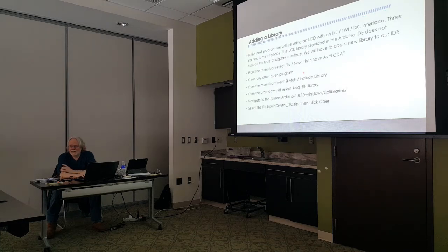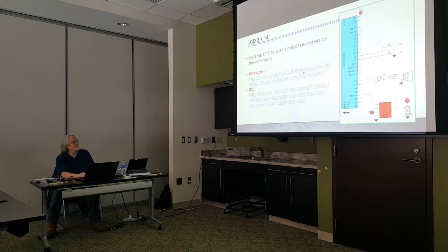Okay, the next thing we did was add a library so we can, I think, run the LCD. Now, if you looked at the libraries available in the Arduino IDE, they had an LCD library, but it was, I believe, a parallel interface. And so it took 10 wires, which means it used up 10 of your port bits, where this uses 2. This uses the I2C interface. And so you have to download it. It's not part of the Arduino IDE. So these instructions just showed you how to load it, how to include it.